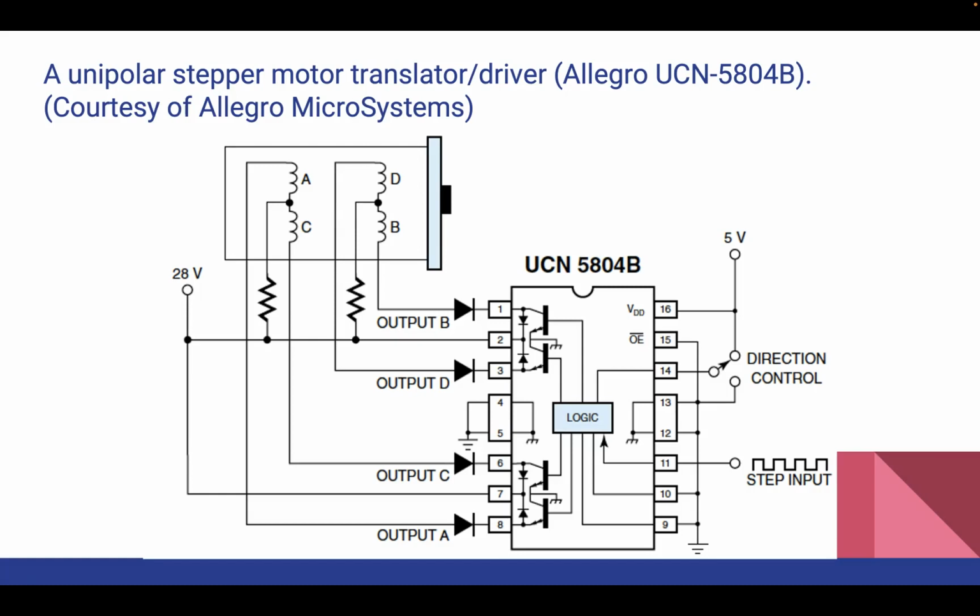And to the motor coils, we simply attach them between the output pins and the supply input voltage. So these are our motor coils in between the output and the supply input. When an output transistor is activated, it completes the circuit by providing a path to the ground for the motor coil current, and thereby it drives the motor's movement.